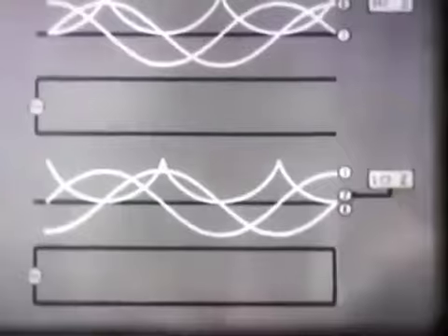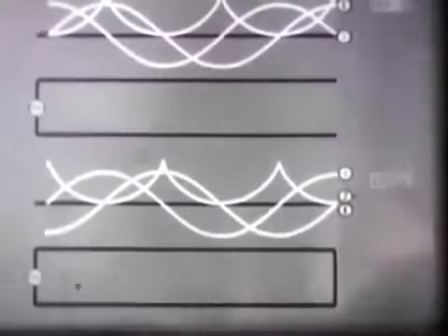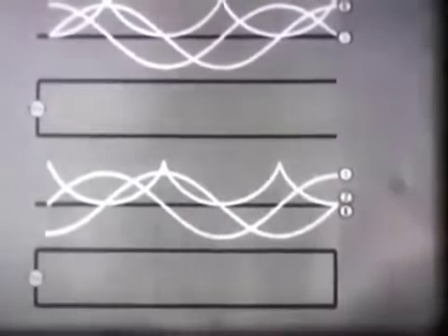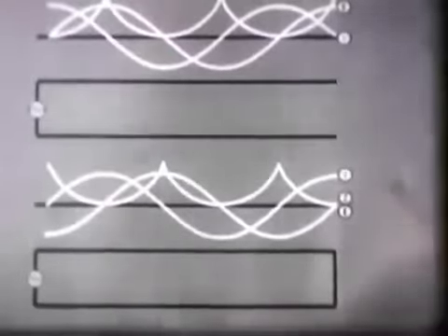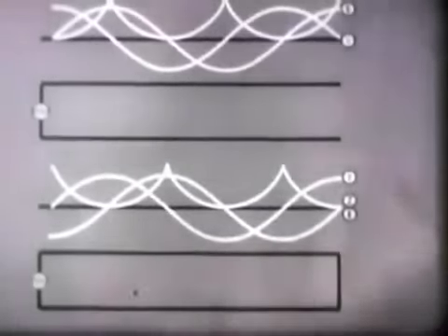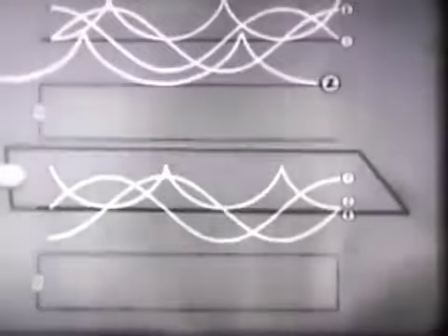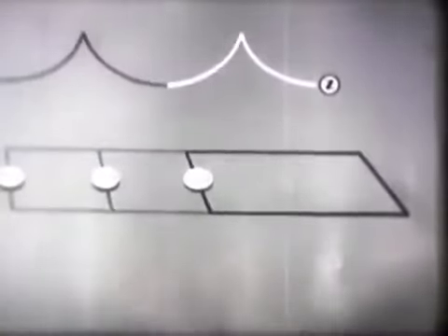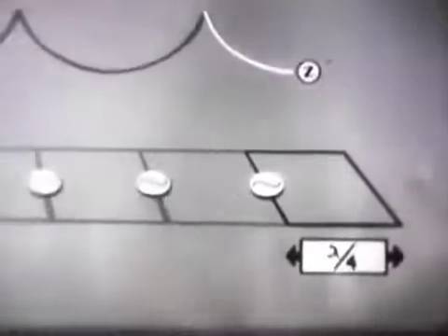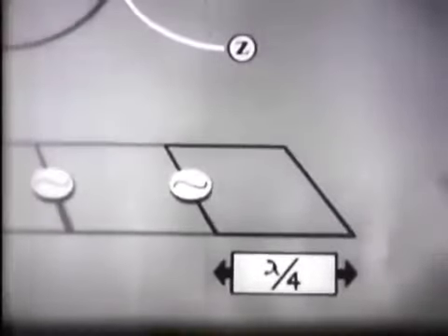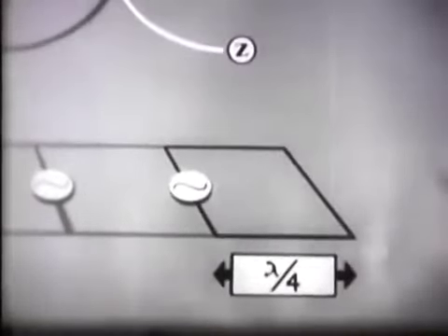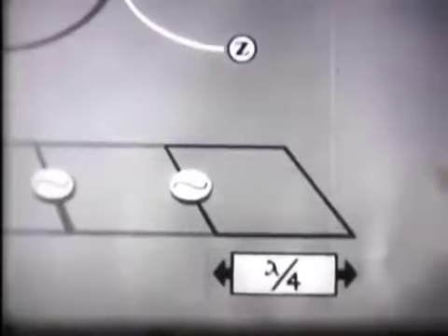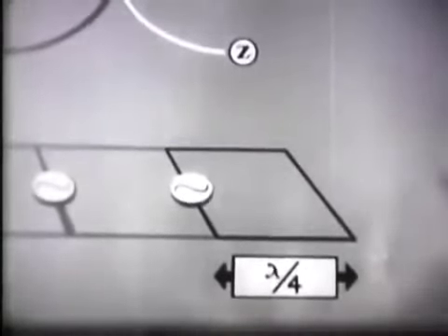With the same frequency applied, a comparison of the shorted and open lines shows that the curve values are reversed. How does this apply to radio antennas? Well, let's shorten our closed-end line and find out. Now we're working with only a 1/4 wavelength of a closed transmission line. The impedance at the terminals of the generator is maximum. In other words, the generator sees the circuit as one of maximum impedance.